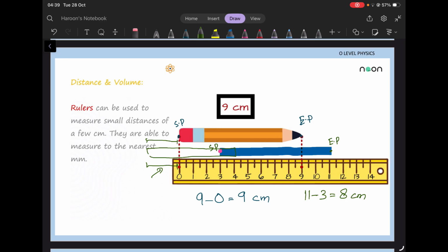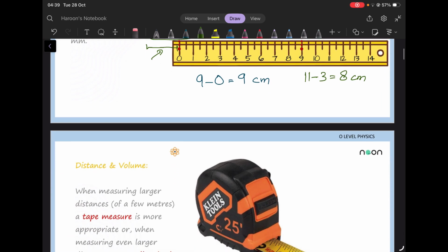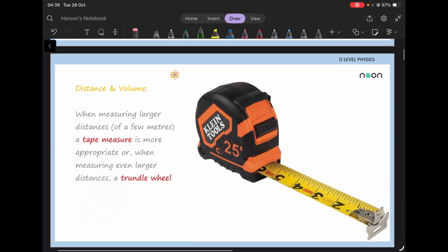So for example, we have those weighing scales. Sometimes they might start from, let's say, 3 kg, and if the weighing machine shows 83, it does not mean your actual mass. It shows the mass, but it won't tell you that the mass is actually 83 kg. It would be 83 minus 3. You need to adjust for the extra 3 kg it showed initially before getting your mass, right? So we need to adjust for the zero error in both cases, positive or negative.